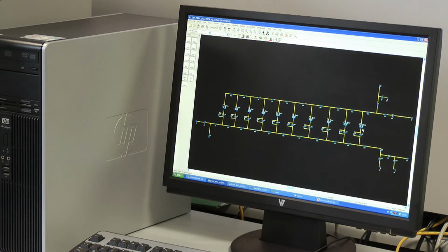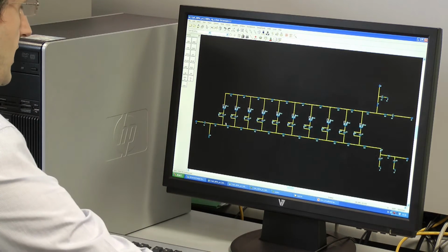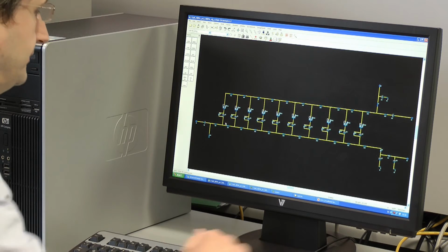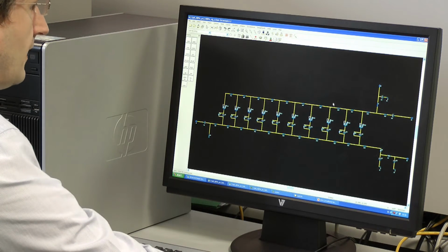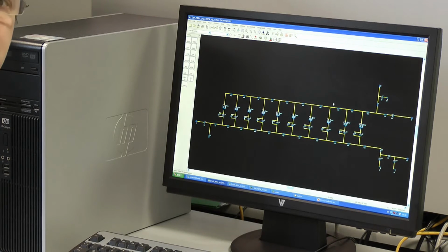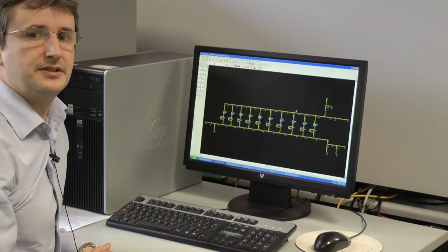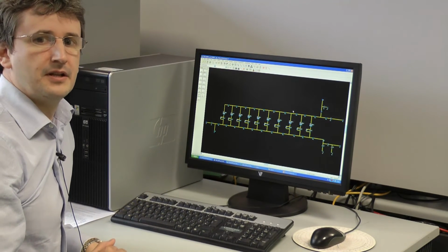One technique that we have used is to taper the value of these series MIM capacitors such that the drive level on each device input is equalized. So they all compress together, which is far better for large signal performance. Now, in a conventional distributed amplifier, the device drains do not necessarily see their optimum impedance for power.